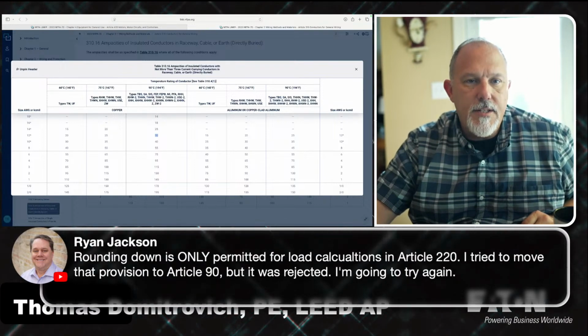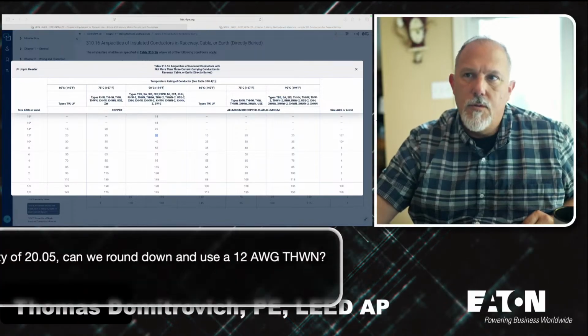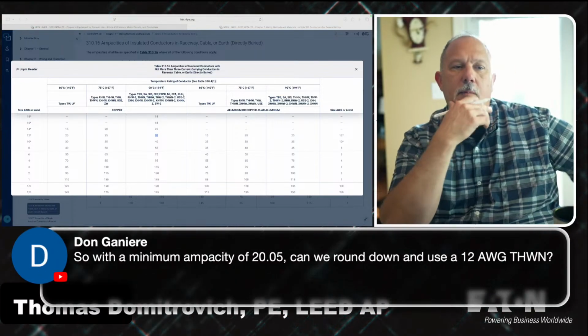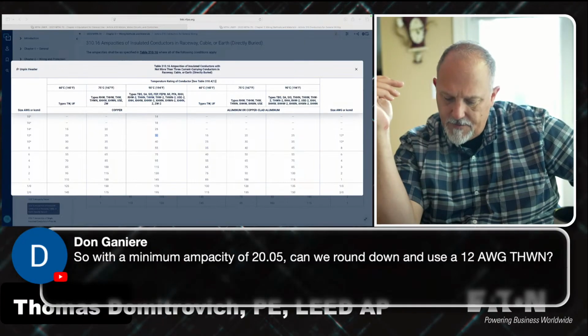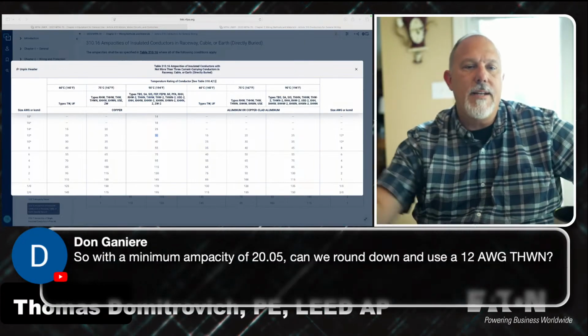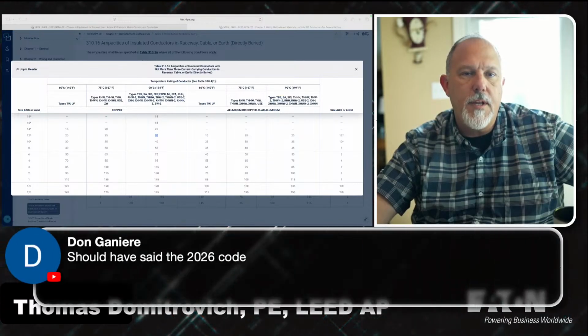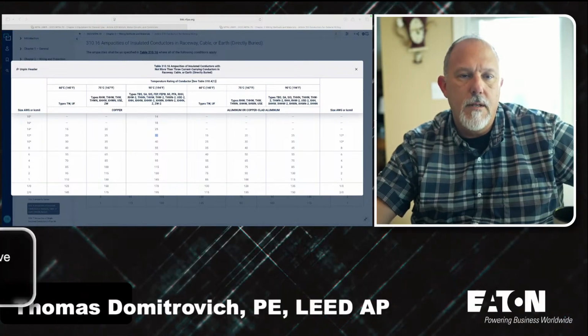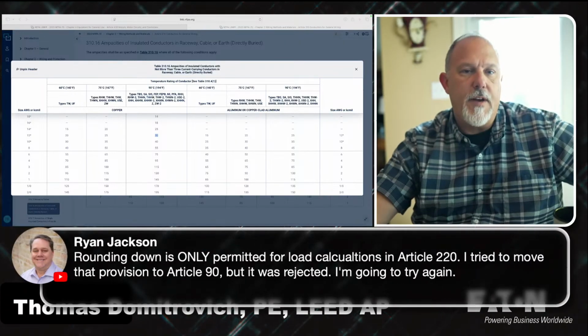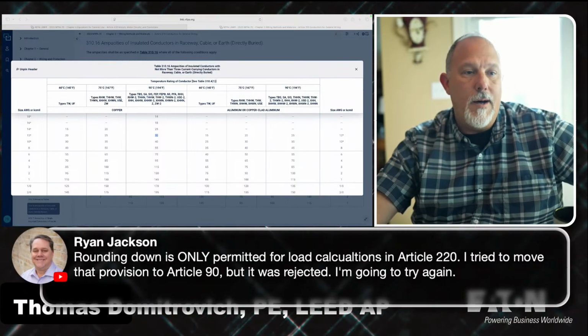What's Dawn saying? So, with a minimum ampacity of 25.05, can we round down? Nope. I don't believe you can. Nope. No, you can't. I have 25.05. I've got to go up.